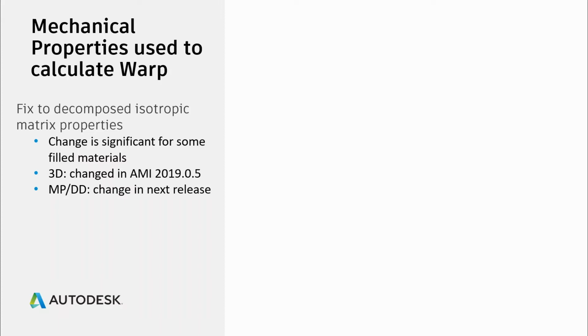For most materials, there is no significant change, but there is a change for some materials. And this change was already introduced for 3D solutions in the Moldflow Insight 2019 Update 5 release because it had a significant effect on the warpage prediction in 3D. However, we did not make that change yet in midplane and dual domain, and we will be bringing in the change of this decomposition accuracy improvement for midplane and dual domain in our next commercial release.